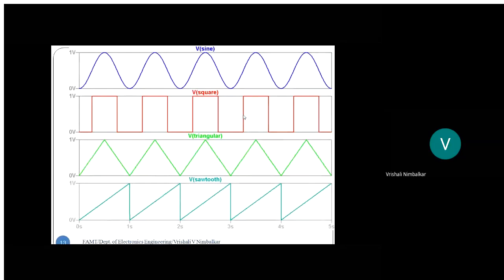See here, I wanted the sawtooth or the ramp. Look at the lowest waveform. This is the ramp or the sawtooth. The output voltage linearly goes on incrementing with respect to time. When the digital input is 0, the analog output is 0. Then the next digital value and the corresponding analog output go on incrementing, and at FF it reaches the maximum limit.